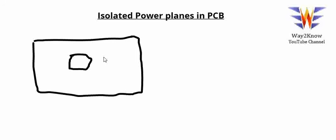These scenarios can be used, for example, when we have a circuit that could be a high frequency operating circuit, or a very critical circuit with respect to functionality, where it needs to be isolated from the other sections. For example, a clocking circuit, a clock tree kind of circuit, or a simple oscillator near the microcontroller or the processor.